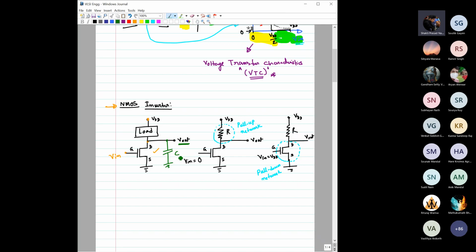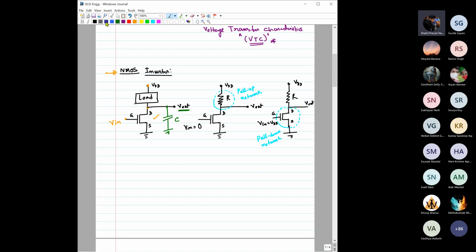Your answer is correct, but I just wanted to know. Store charge, but what is the fundamental reason, why not resistance? It could store voltage, which would help in providing the input to the next stage. Right, because if you are designing one inverter, it is expected that the output of this inverter is also driving another gate. Maybe it is another inverter, or maybe it is an input to, say, a NAND gate, right?